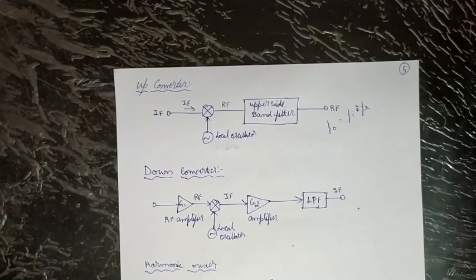The intermediate frequency oscillator is modulated with the desired information signal, which is mixed with the local oscillator signal to generate the desired frequency conversion. Use of a mixer as an up converter, particularly in the case of radar or transceiver work, is advantageous because it allows use of a single local oscillator for both receiver and transmitter.